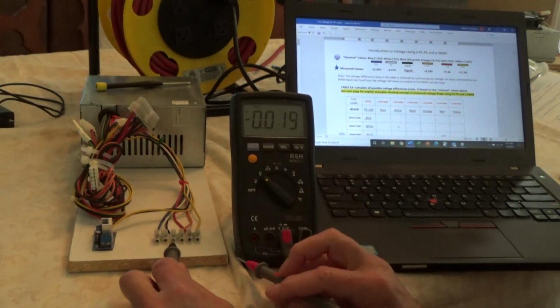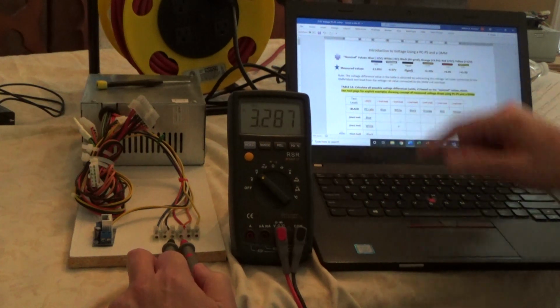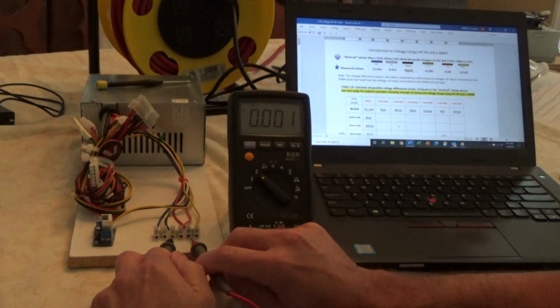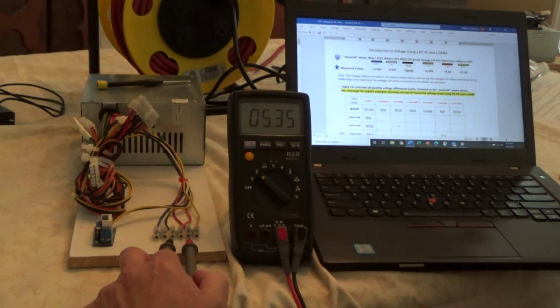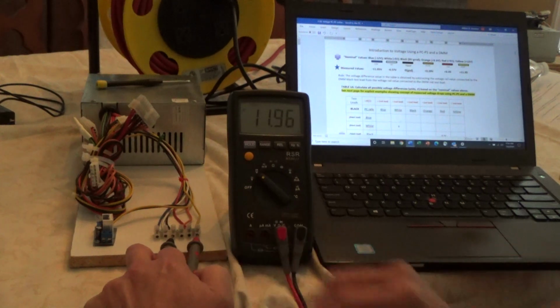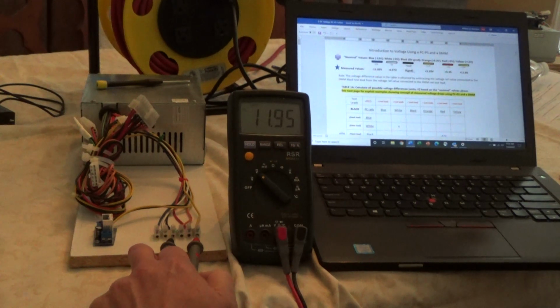Okay, now let's go to the positive rails. The 3.3 volt rail, I just rounded that off, is 3.29, so that still agrees, plus 3.29. The red rail, or the 5 volt rail, nominal 5, is actually 5.35, and that's pretty common. I've noticed that on a lot of computer power supplies, the voltage on the red rail is generally higher than 5, like that's a normal value. I don't know why we even call it a 5 volt rail. Okay, anyway, so there you go. And then the yellow rail relative to ground is plus 11.95 volts, and that agrees with what I wrote down earlier. I hope you can see all this.